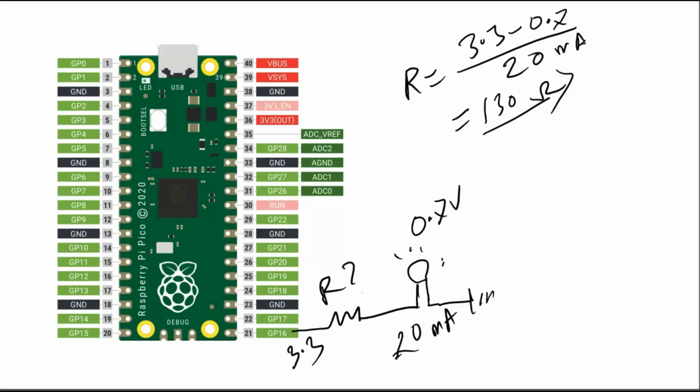But if we connect a resistance of very high value, then the LED might dim a little bit. So just be careful about this one. For today, I just chose 220 ohm in my case. So it will be a 220 ohm resistance for this one. I think the circuit diagram is pretty simple and it's very easy to choose the perfect resistance for today's project. Now let's connect the circuit on the breadboard.